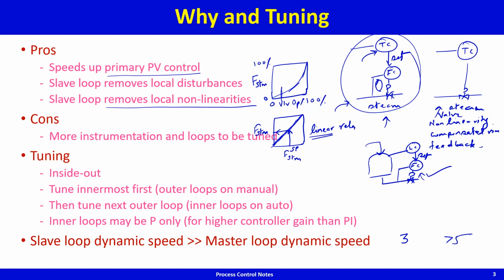The other thing that I wanted to say was, in chemical processes you have this time scale separation. For example, if you look at a distillation column, making a change to the reboiler duty causes a change in the boil up, and the change in the boil up will cause a change in the tray temperatures immediately.